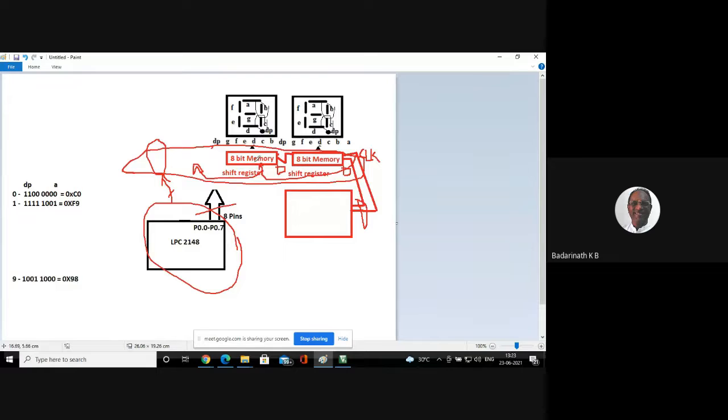The next shift register. Similarly, when you push the data, again another 8 bits, the data that is in the second shift register will go to the third shift register. So this concept is called cascading of shift registers, and designing the 7-segment display using only 2 lines of the microcontroller is very popularly used because we reduce the number of lines to realize a display system.